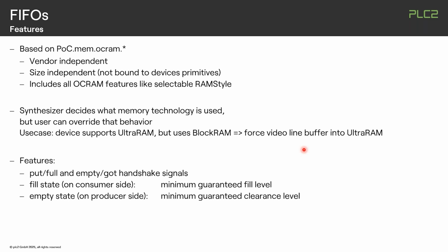If you set the number of bits to the logarithm of 2 of the whole FIFO length, then you get a word by word fill level, but usually this is not needed in designs. Indications like quarters or eighths are already enough for most use cases. And this saves resources in the internal implementation.